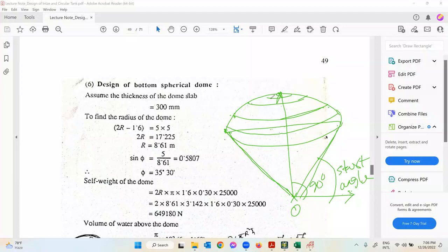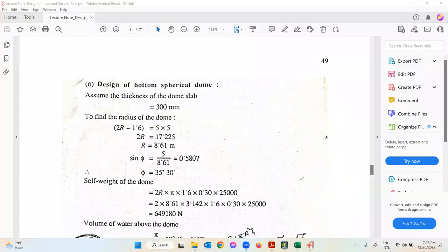And the latitudes are the vertical lines. These are the ones. Okay, how many of them do you want? So based on these numbers, your plate size will be either smaller or bigger. If you use too many of them, the plate size will be smaller. That means the calculations will be more accurate, but it will take more time for STAAD.Pro to give you the results. Okay, that will be computationally intensive. So I hope you understood what we mean by these parameters. Let me go back to STAAD.Pro again.